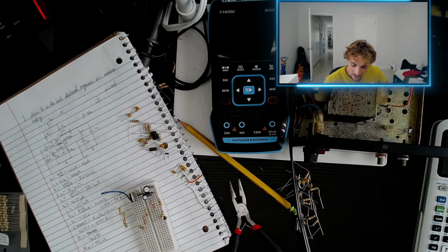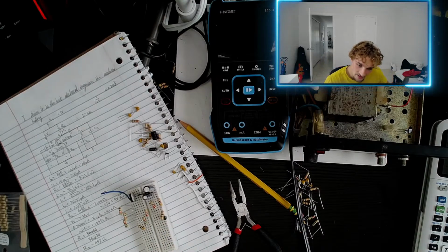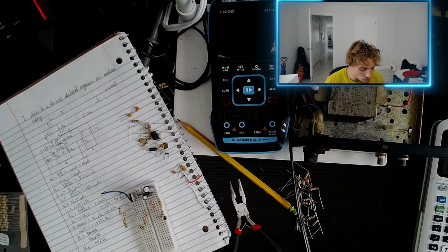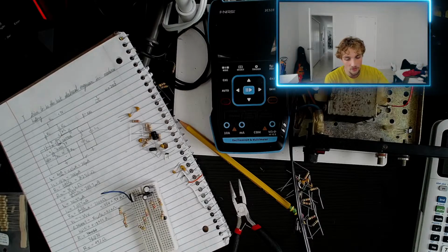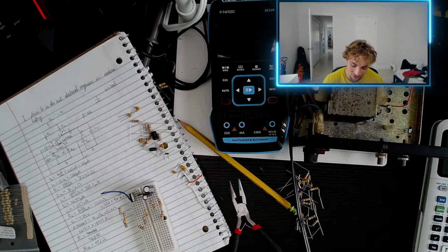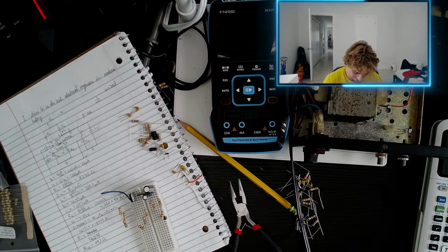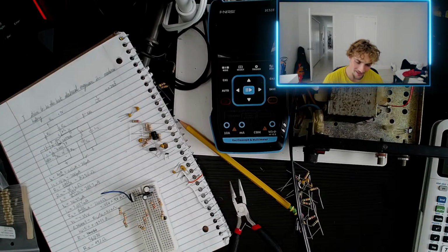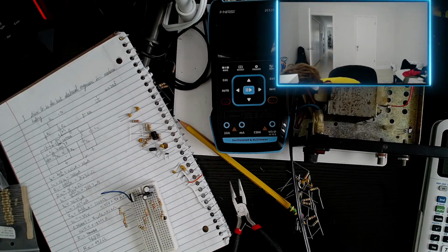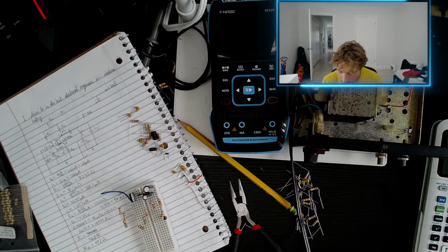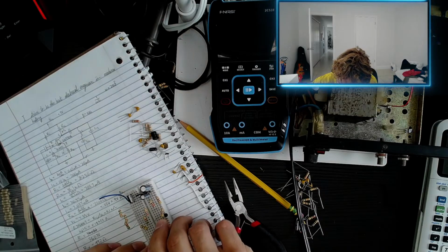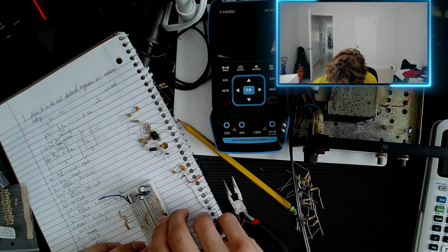All right, and now our collector side. Our collector resistance has a value of 2200, and we have exactly that. We have a 2.2 kilo ohm resistor, so that's perfect. Just one resistor. Ha! That's beautiful. This is what we desire. Indubitably. Do I have one out here? I don't. Okay. All right, and he's gonna connect directly to our supply, so we'll figure that out in a moment.